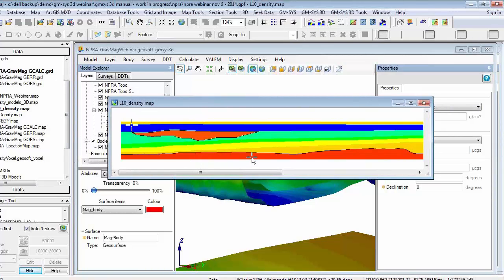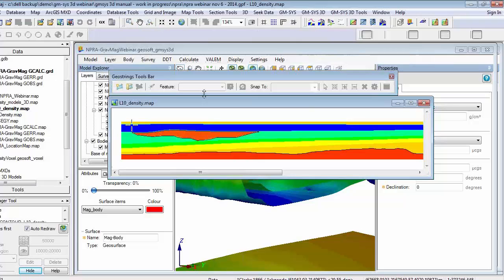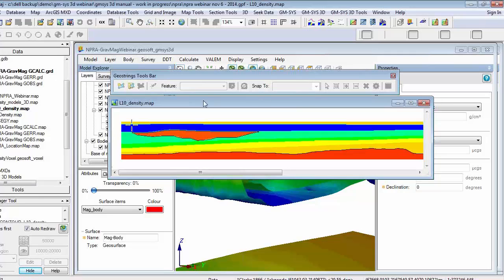And when you're building out these, you would use this wireframing tool capability, and if any of you are particularly interested in that, we can certainly get you step-by-step instructions on how to create the wire strings. In the interest of time, I won't go through this step-by-step, but essentially what this allows you to do is to digitize this black line that I've digitized before, and when you digitize them on these lines, you can then connect them in a 3D environment to build out a closed surface, which is a great way to incorporate small bodies and that detail that you have from the 2D sections.